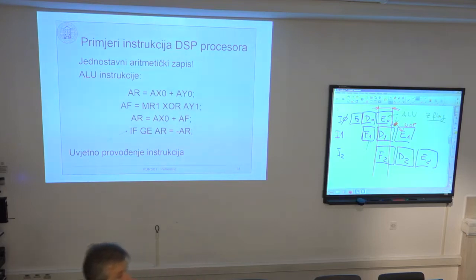Sometimes this is done in hardware. So this pipeline controller, as a part of the architecture, does all of this checking of interdependencies between one instruction and the other instruction. But of course, since you have an enormous number of combinations of instructions, this hardware is very complex. It must identify all the possible combinations where this pipeline collision, but stall, can occur. And for that reason, it complicates the hardware implementation.